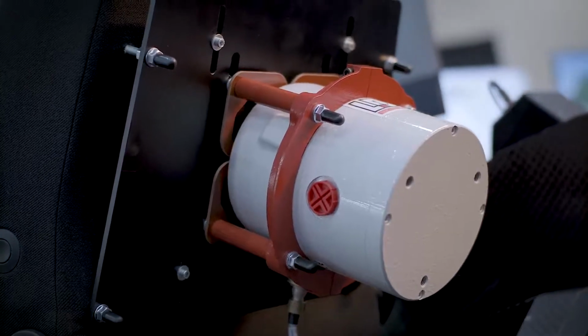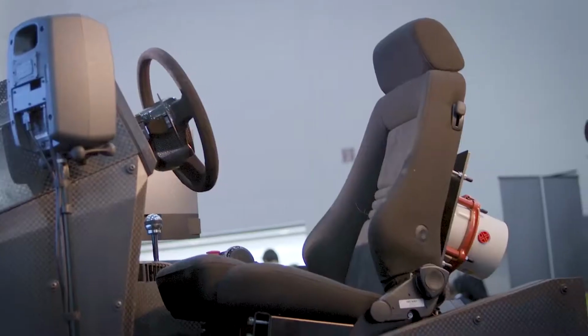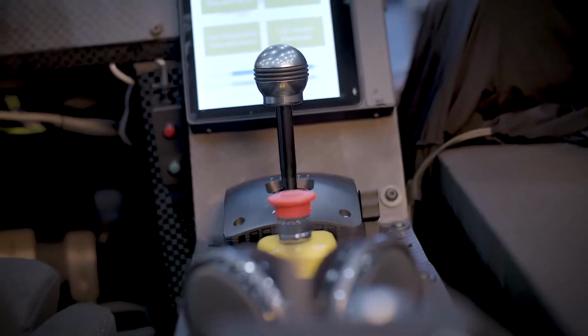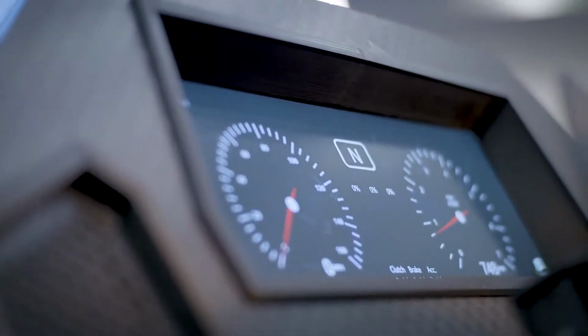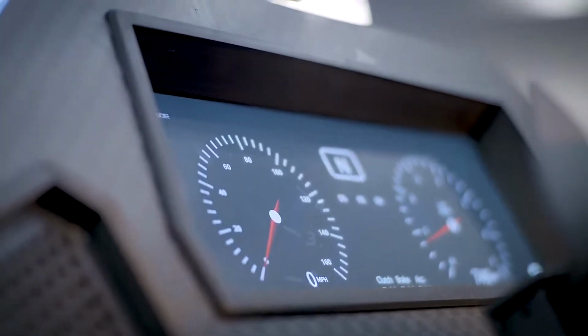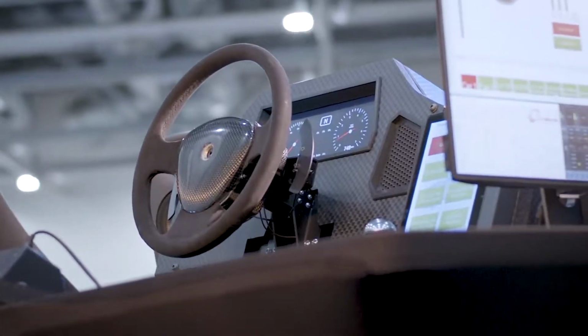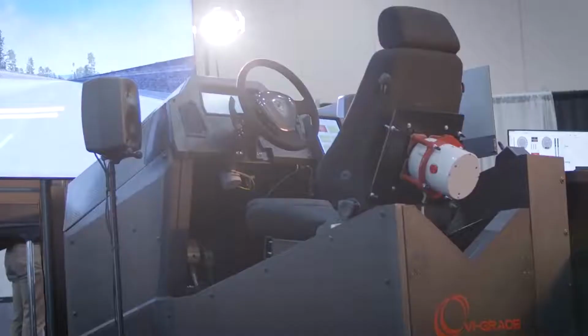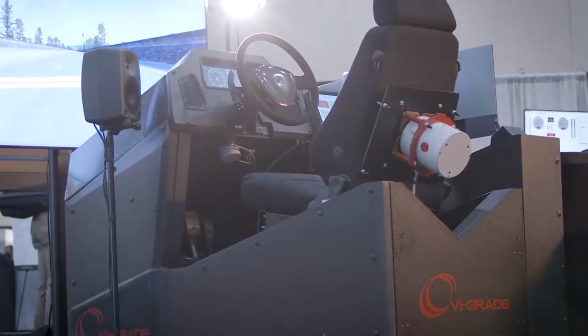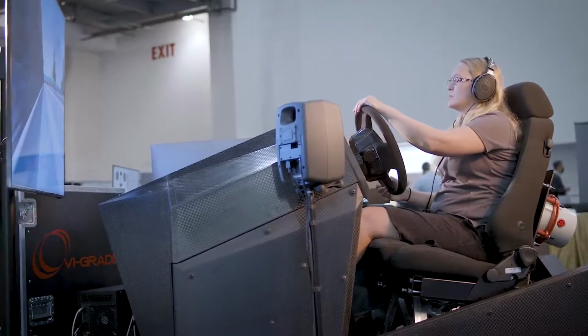Accurate, calibrated, multi-axial vibration is provided at the seat, steering wheel, and floor pan. Each axis of vibration can be independently controlled, and each axis is independent from all others without crosstalk. So when the steering wheel vibrates, it does so completely independent from the seat. The seat does not vibrate due to the inputs to the steering system, or vice versa. This provides engineers with the ability to understand the trade-offs between vibration levels at different driver touchpoints, as well as sound levels. It also enables driver-in-the-loop free driving of NVH virtual prototypes.